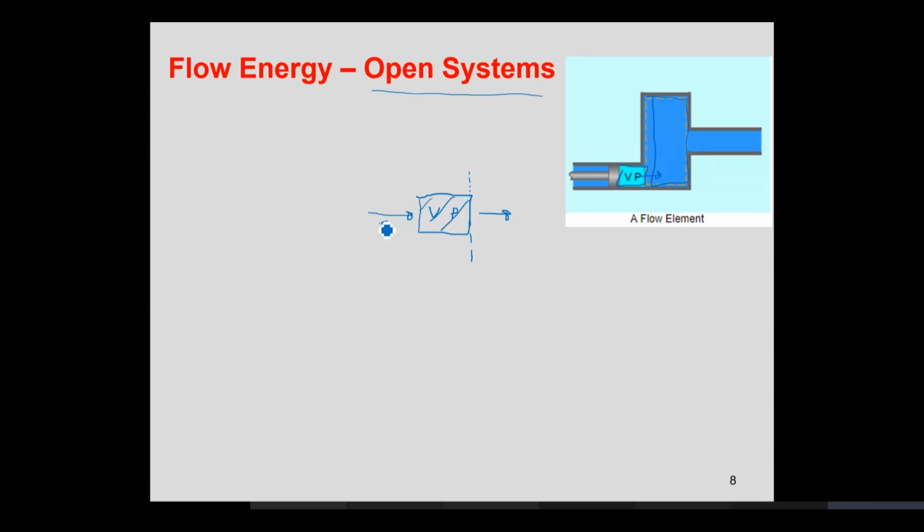The resistance to the flow is caused by the pressure of this chunk. To overcome it, the force needed from the fluid at its rear is essentially pressure multiplied by the cross-sectional area of the element.